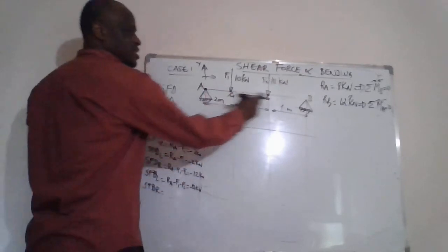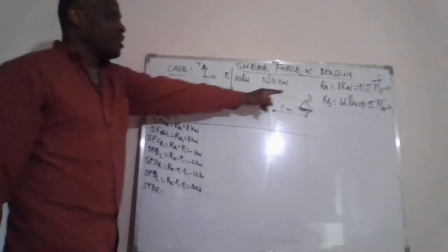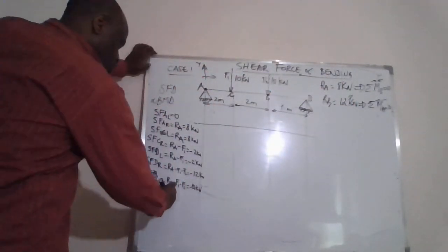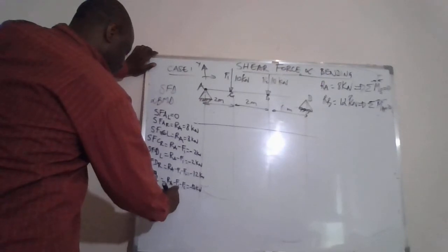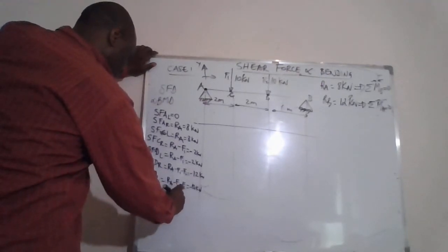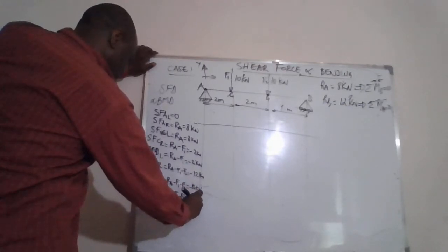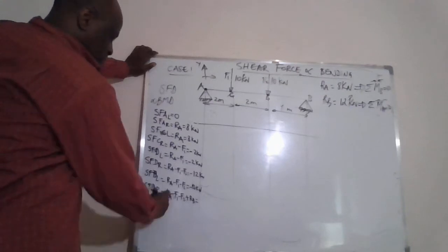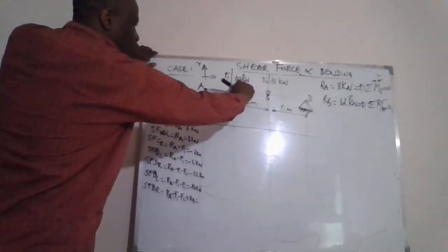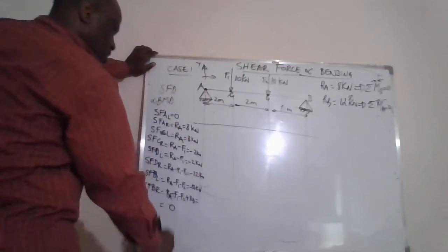It means we have the sum of reactions and the sum of loads. If our reactions are properly calculated, we should have 0. It means we'll have RA minus F1 minus F2 plus RB. RA being 8, RB being 12, these two, 10, 10, 20 minus 20 will be equal to 0.